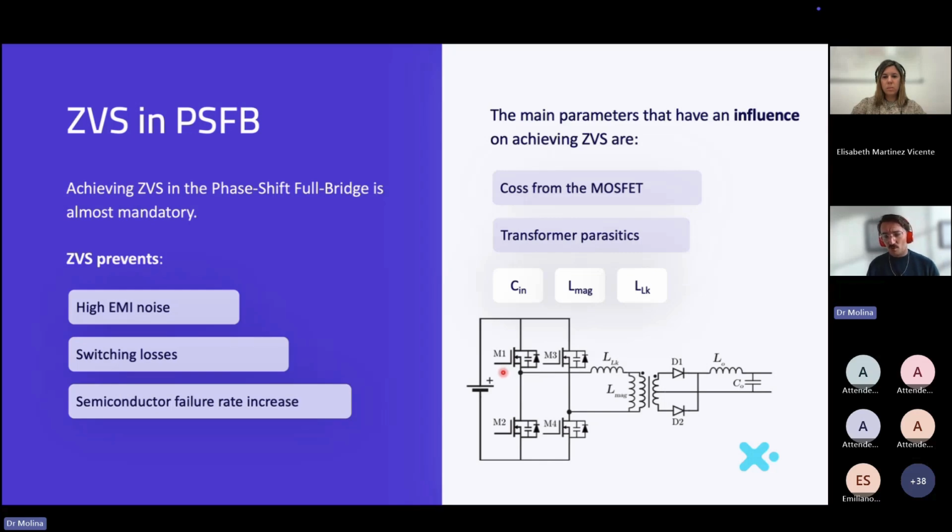We are going to focus on the 2 main ones: conduction losses, that are the ones that I was saying about. You switch on this MOSFET and then the current goes through the MOSFET. So you have conduction losses, and then you have switching losses. The switching losses are the energy that you need to make this switch turn on or turn off, so change the status. And the switching losses are mainly due to the parasitic capacitance that you have in this switch, but also about when this is happening.